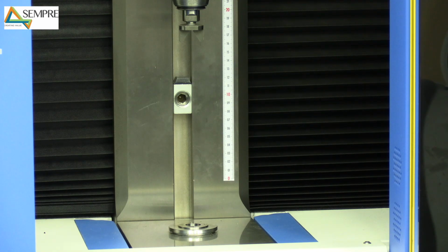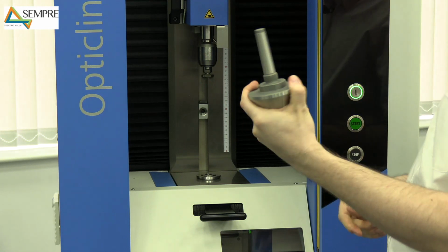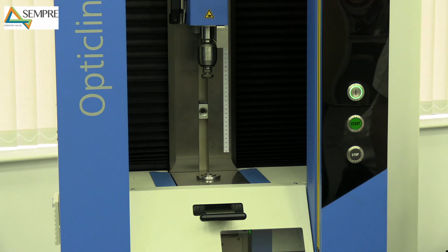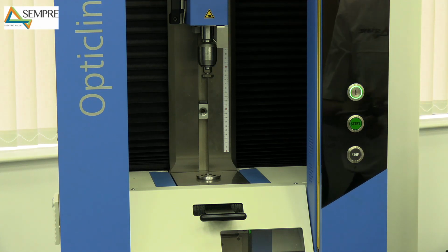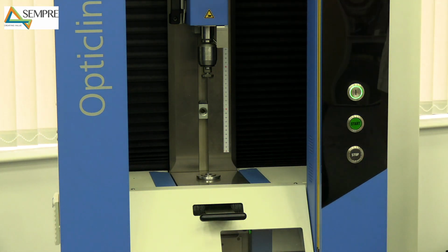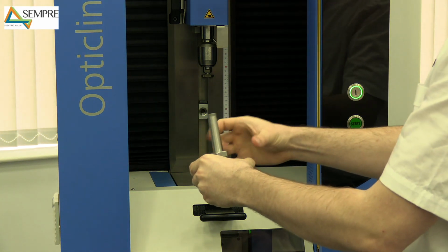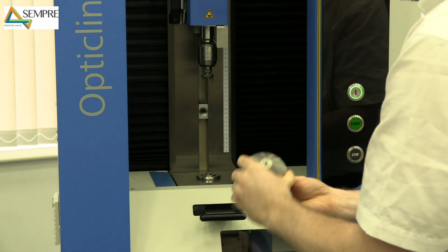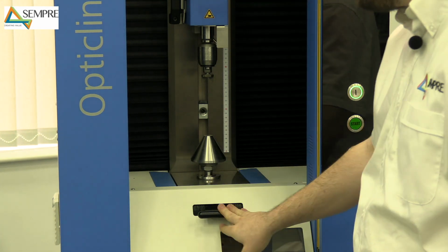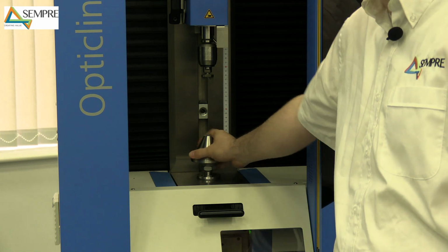and then whenever you put a center in the Opticline, you just want to make sure, for example on this center here, that you put a locking nut on the thread. So I'm taking the locking nut off a previous center, screwing it down, and then placing the center as such in the machine. And now it's in there, and I've unlocked the axis. That's free to rotate and hold any part that you like.